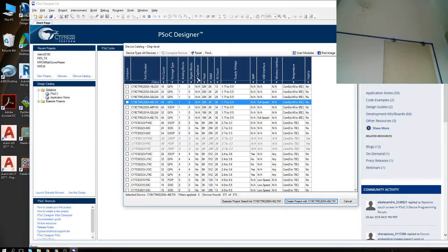I have a capacitive sensing area here. Fundamentally, it's just like an antenna. And what happens when you put this one in water? The surrounding material changes, which means that the capacitance changes. So you're changing the permittivity around this sensor. And okay, now I have a problem: how to sense the capacitance.